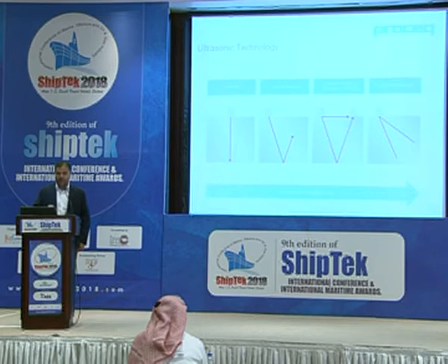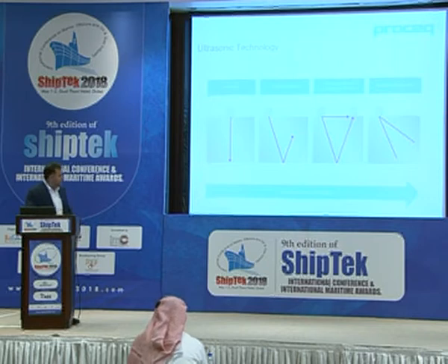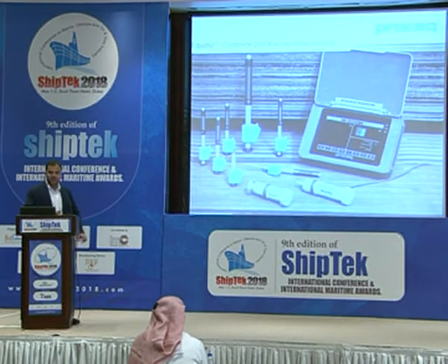Having a quick look at the ultrasonic technology, basically for thickness, this is the principle we are talking about. It's an echo. We send the echo and then it is received back, that is the conventional UT. And when it comes to TOFD, the time of flight diffraction, if there are any defects, we can size the defects, and also the phased arrays. I'm not going to look deeper into flaw detection. However, we'll just talk more on the portable hardness testing today.